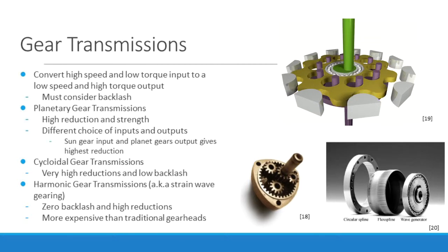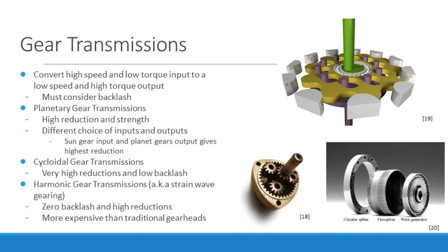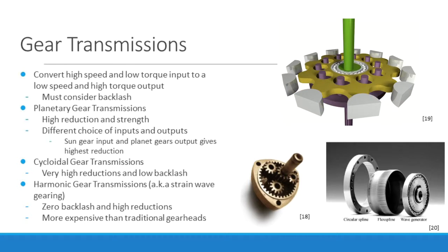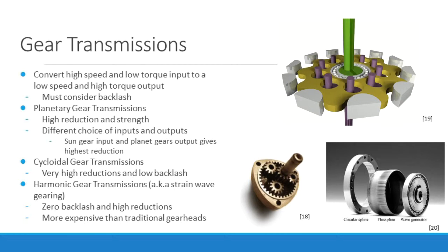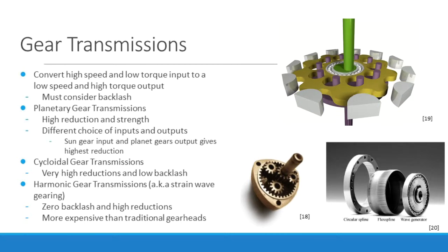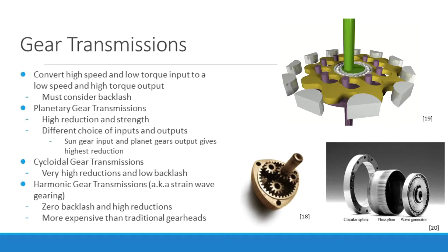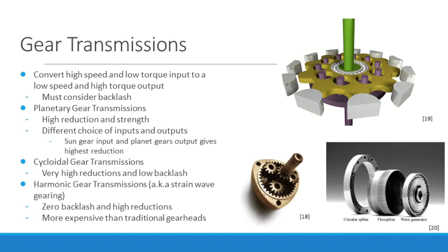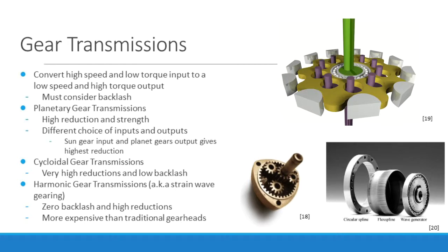The right combination of gears can make these transmissions have a very high reduction ratio, and since load torques will be distributed across the planet gears, these transmissions are also high strength. Cycloidal transmissions are another high-strength and high-reduction mechanism that uses an eccentric disc and a set of rollers to provide a large gear reduction ratio in a very compact space.